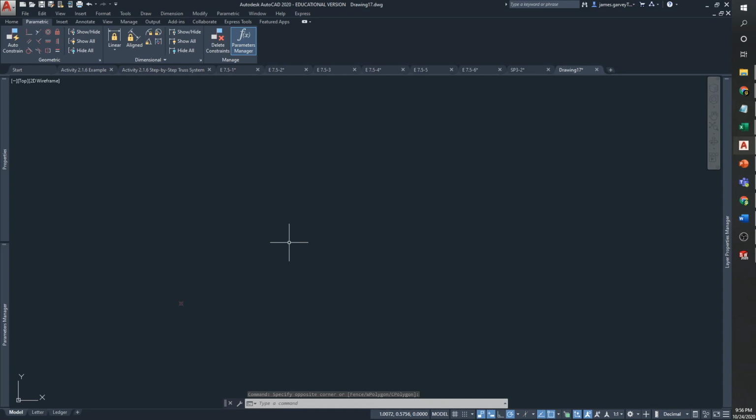Before we start applying our parametric constraints to orthographic views, I want to show you how to update your templates to make the whole process go faster. So what I'm going to do is make boxes for our front, right, and top views that will control the height, width, and depths of your three views. So I'm just going to dive in right now.